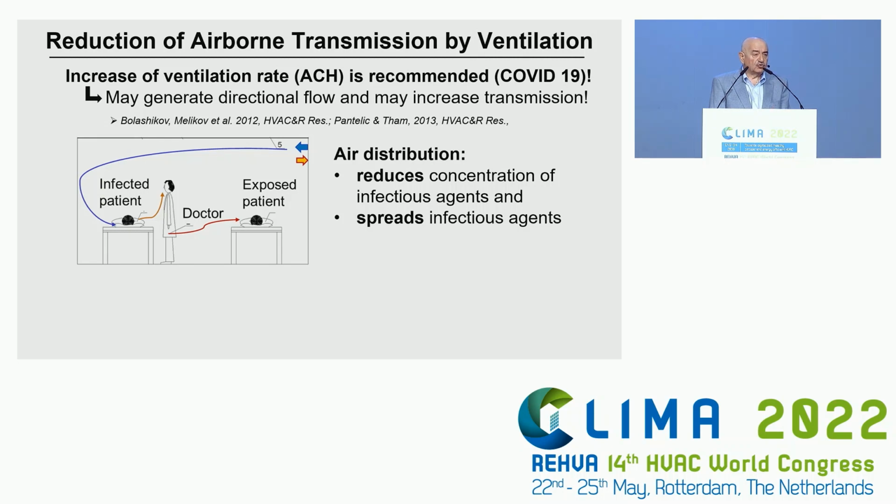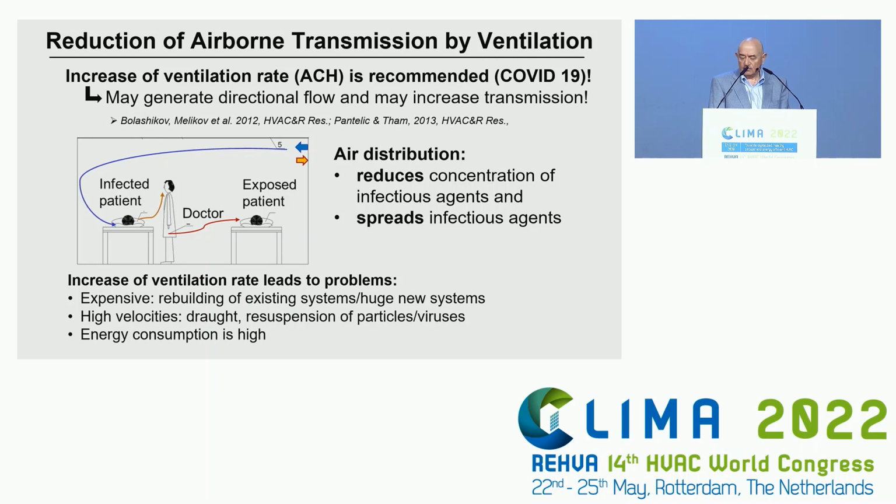The figure shows how supply air might be distributed and how it will spread the pollution. In fact, exposure of the doctor and the patient in bed may increase. So it's very important to remember that not only do we reduce the concentration of viruses, but we may also spread them in an undesirable place. Of course, there are other disadvantages of increasing ventilation rates: systems become more expensive and bigger, we may cause discomfort, and energy use will increase.